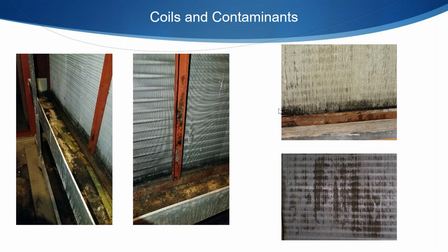Biofilm growth is actually worse for your system efficiency than even the blockage that mold can cause, because it starts as soon as you're done cleaning the coil and you start up your system. You have the potential for that biofilm to start growing on all the surfaces of your coil. As it does, your coil loses that metal-to-air surface contact and instead has a biofilm, which is not nearly as conductive as the metal. So you're losing heat transfer efficiency through that biofilm growth. And it's not as visible, so it's disregarded. It's pretty highly disregarded as not a concern.